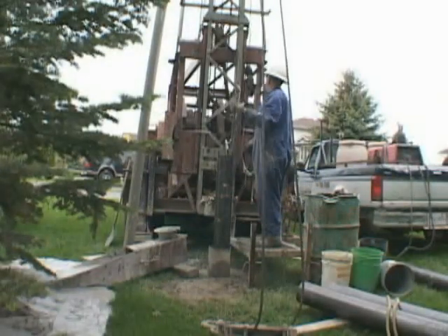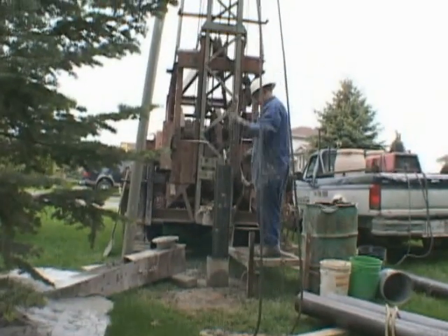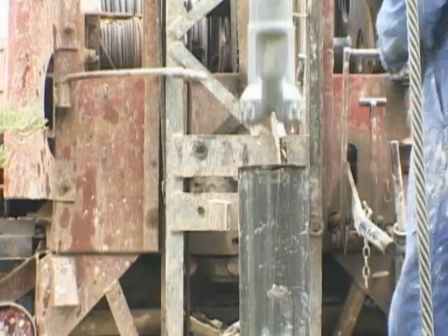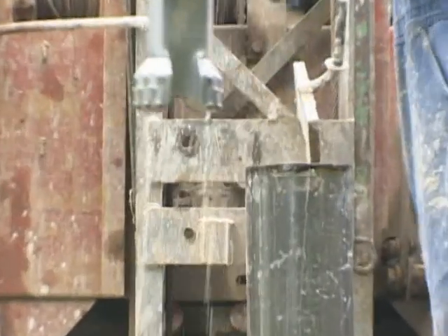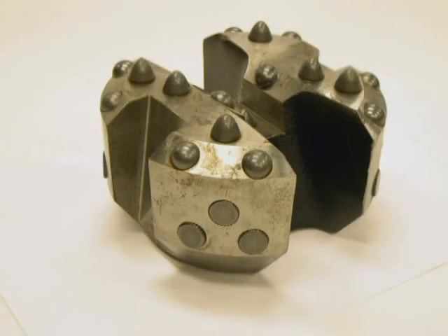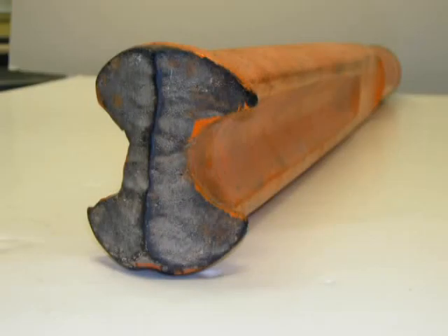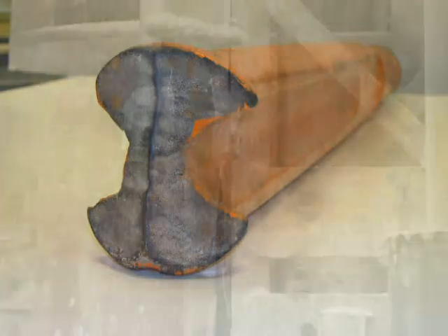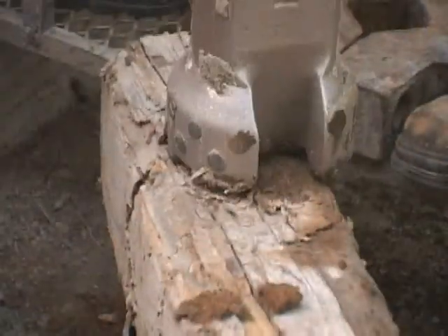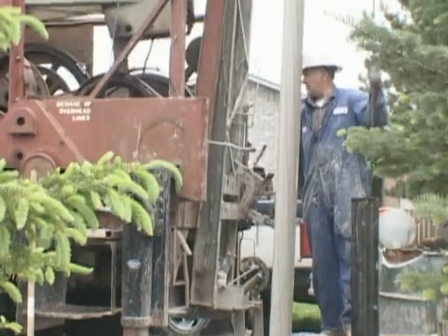The percussion cutting action obtains its striking energy from the drill string components, which consist of a 1,200-pound, 22-foot-long drill bar and the drill bit. The drill bar is fastened directly to the bit, which contains either carbide buttons or a hardened steel chisel face. This drill string assembly is lifted 22 inches and then dropped, allowing the bit to perform 4 important functions simultaneously.